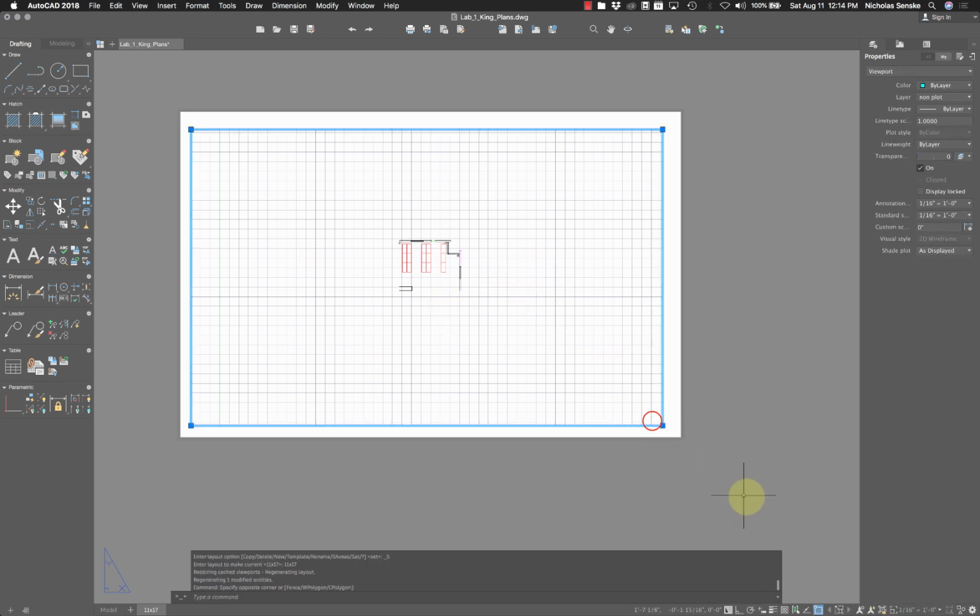So let's look at it. That's 1/16 scale. That is not appropriate. Let's go to 1/8 scale. Now you can see there are these weird kind of 3/32, 3/16. Let's avoid those as much as possible. The reason why is because, again, like I said before, architects expect things at a certain scale. 1/16, 1/8, 1/4, 1/2, things that are fractions are very easy to understand because they're all halves of each other or quarters. 3/32 is weird.